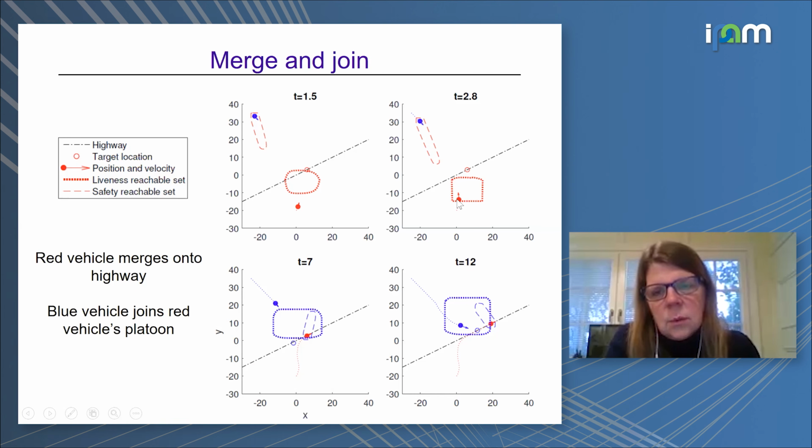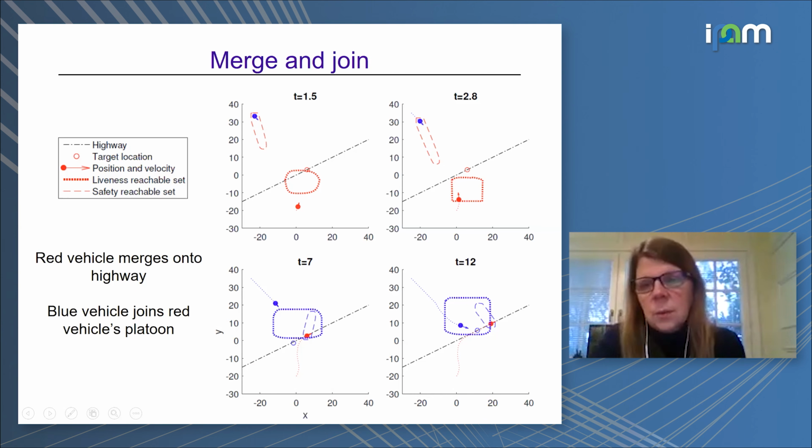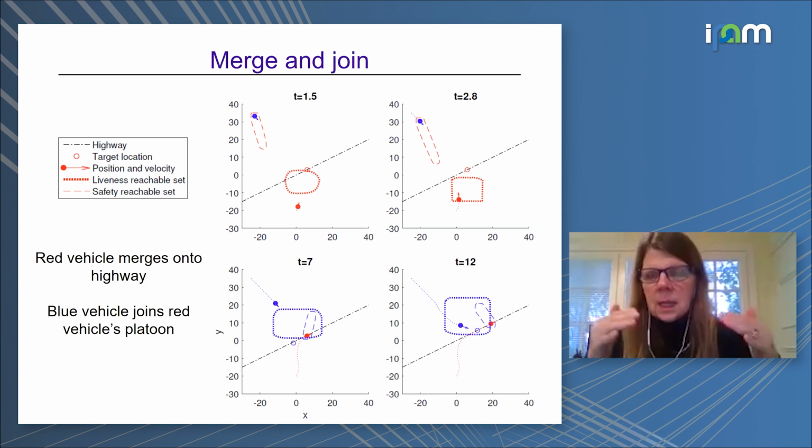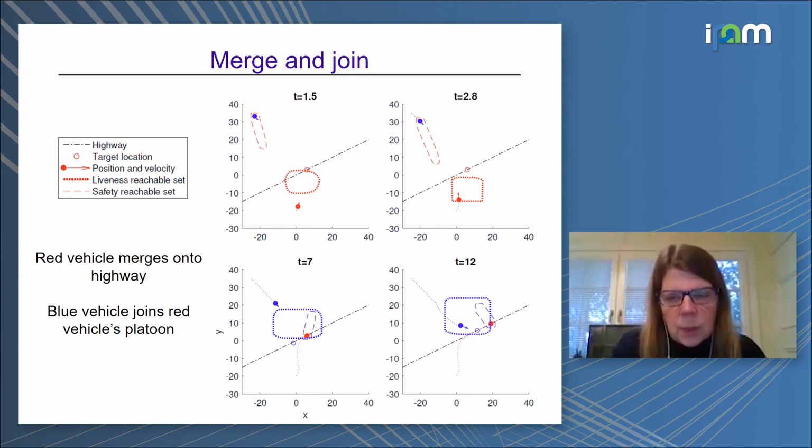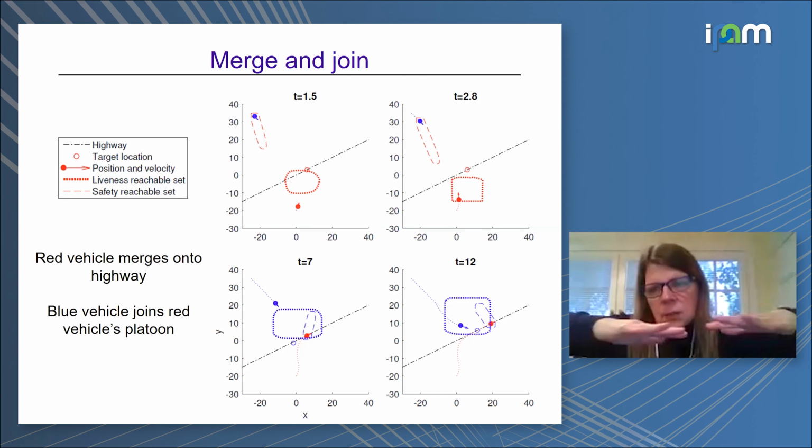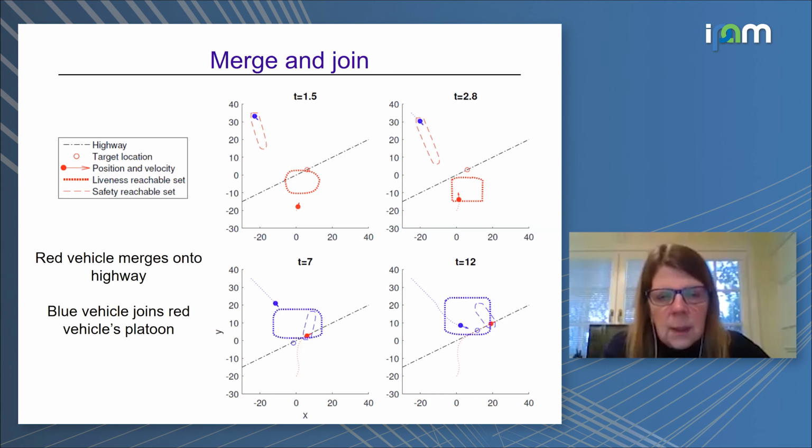And then as it moves, here it gets into this region. You see the avoid region is changing shape because the vehicles themselves are moving with respect to each other. And this is just a 2D projection of a 7-dimensional calculation that we did: 7 dimensions in the relative dynamics of those two vehicles, using both the XY position as well as the dynamics of the relative heading of the vehicles.